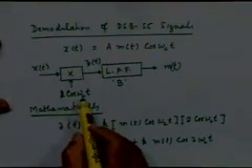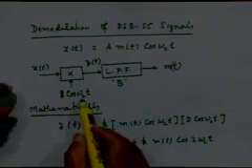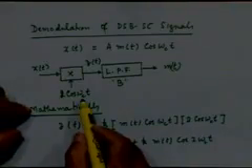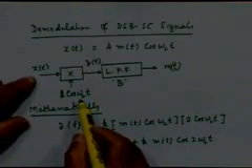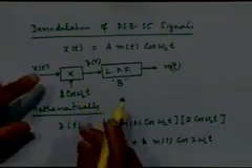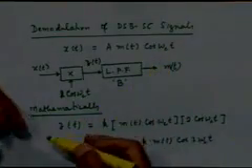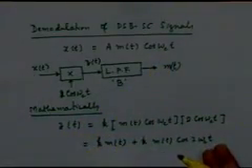This local carrier must be precisely at the same frequency as the one that you have used at the transmitter. It should have precisely the same phase as the phase of the incoming signal carrying the incoming signal. Because if these two conditions are violated, you will not get a perfect demodulation of the kind that we have proved mathematically to be so.